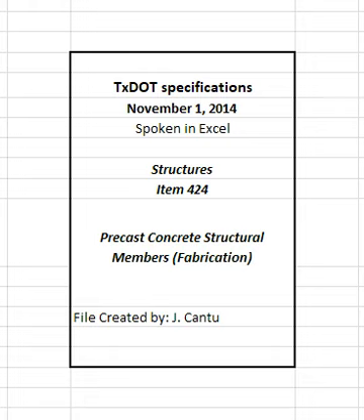Splice void form sections to prevent separation or misalignment during concrete placement and consolidation operations. During casting, verify and document void form placement at 10 feet maximum spacing using an approved method. Vent void forms without solid cores to eliminate high air pressure caused by heat of hydration.